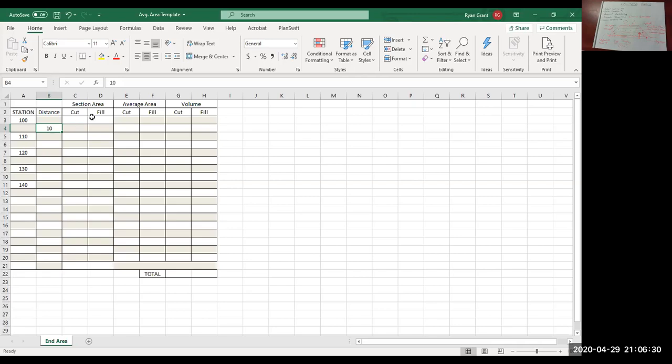Okay, so the next two columns, this is where you calculate your end areas. I'll highlight it yellow. So we looked at station 0 plus 110. And if you, using your scale, measured the area that I kind of outlined with my mouse, you would get something approximately like that. So the area of the fill at this station is approximately 3.9 square meters.